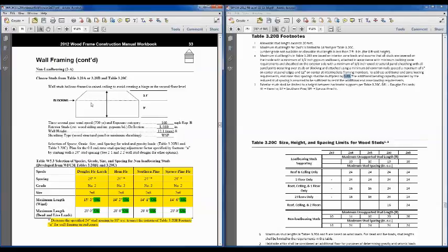What we're looking at here is, because we've got a vaulted ceiling on this end of the structure, we've got 2 options. One would be to balloon frame all the way to the peak, and we actually looked at that in the roof design example last week. Or what we ended up resolving last week in the roof example is this little triangular peak here. We're just going to frame that in.